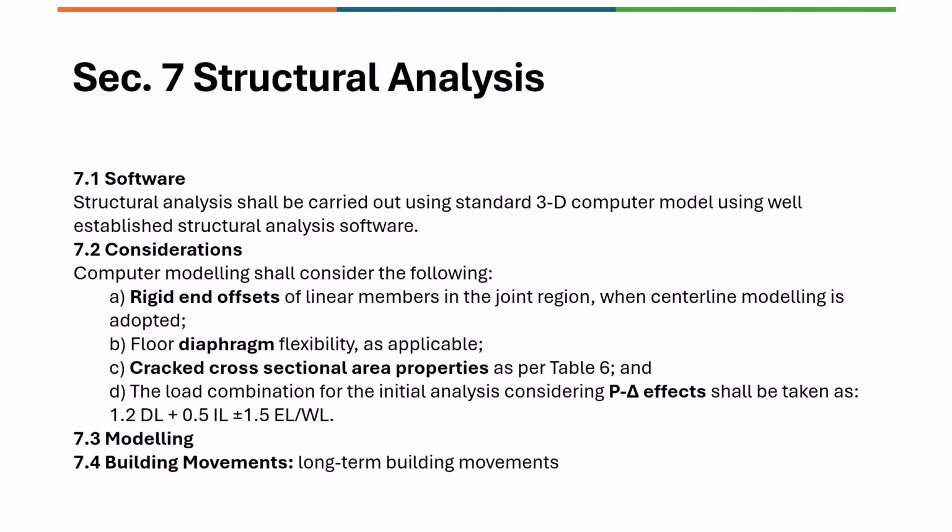And then for the analysis, we have to prepare the model. Other than that, we also have model related, such as stiffness related, for example, foundation flexibility, right? In-plane stiffness or out-of-plane stiffness of slabs, when to consider, right? And the interstory drift, etc. So all of this are discussed under 7.3. We already have all of these features for the modeling.